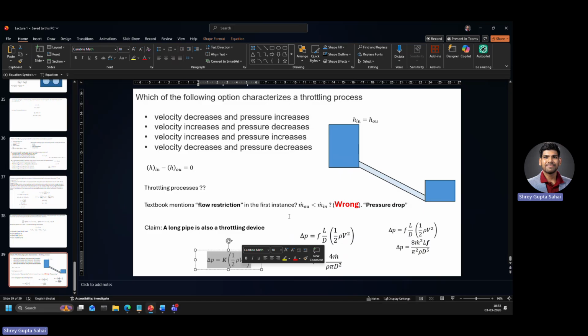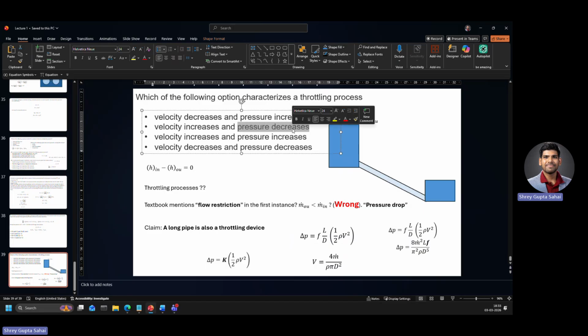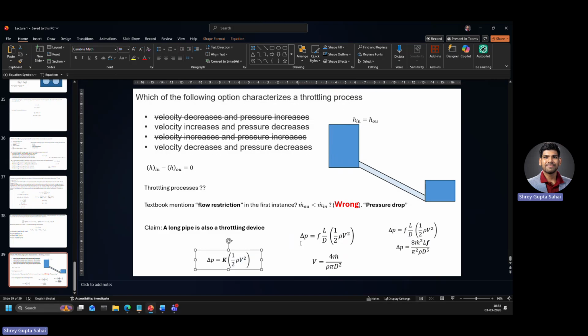So these are two different things. Flow gets restricted by actuating the valve, but pressure drops across these valves by virtue of their existence, or by virtue of flow. Because there is a flow across these devices, the pressures are known to drop across them. Okay, so that is the idea. So between these two points, definitely these two are not correct, because pressure has to drop across flow restricting devices. But as I told you, this is the momentum balance equation.